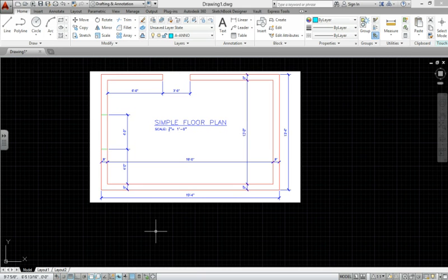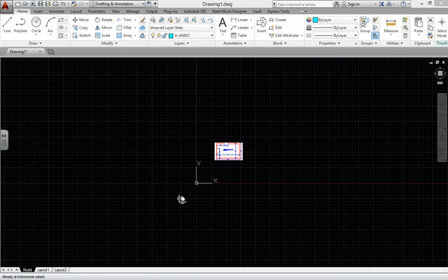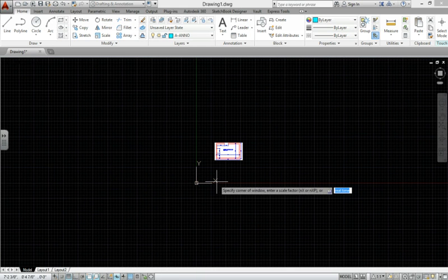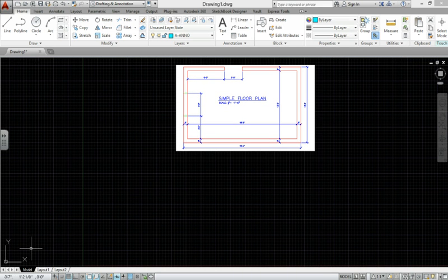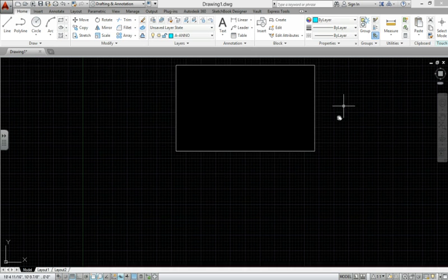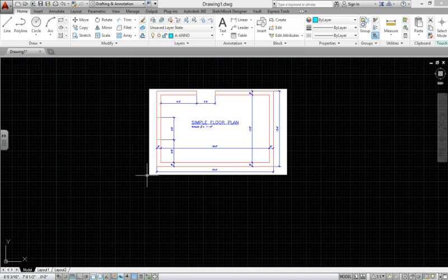Then hit enter. Now the drawing has been reset to a size which is much larger. So if you type in Z enter, all enter, it zooms to the drawing scale. You can see the units down here where my arrow is pointing, where the units are changed from 0 to about 20 feet or larger. I copied the picture here just so that I can see this as I demonstrate. The first method is the line command.